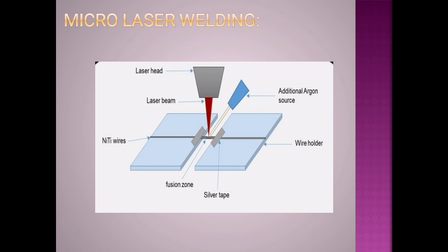At an average power of 100 watt, a pulsed laser performs like a continuous wave laser, emitting several hundreds of watts. This happens due to high pulsed peak power, which breaks down the reflectivity of the surface, which results in the laser energy being absorbed more efficiently.